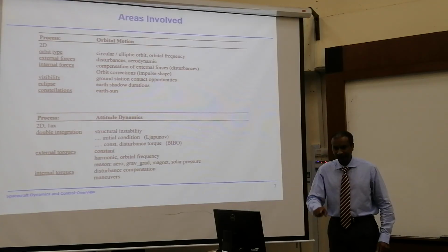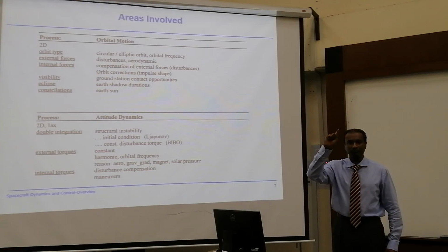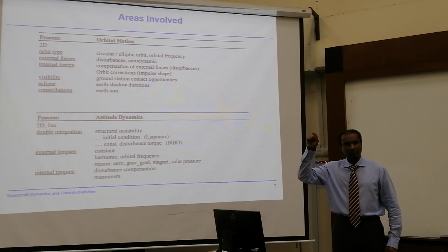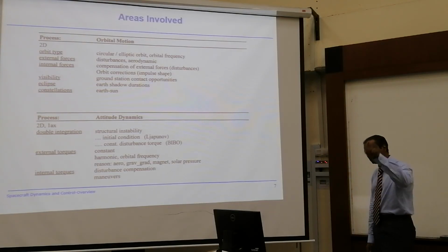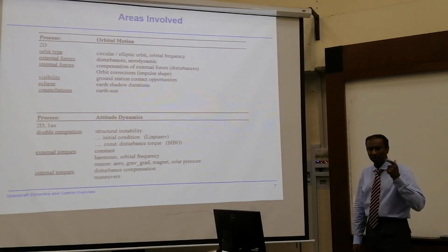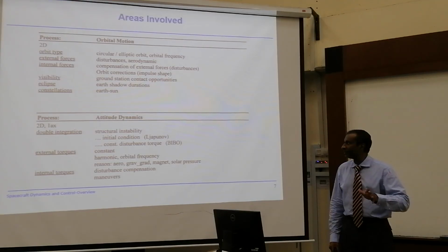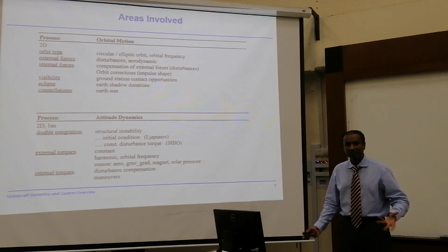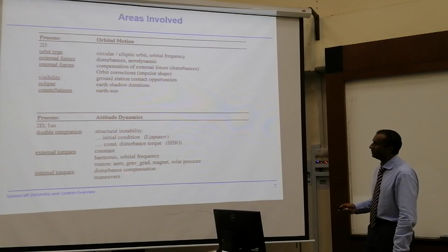That means what? Impulse means you have learned this in satellite technology, propulsion system. On, zoom. Let's say 0.1 Newton, 1 second. So it's impulse. Okay, it gives you impulse just like that. And close. It's open, close. Propulsion system, open, close. That's it. Attitude, open, you don't close until the mission dies. So that's the difference.